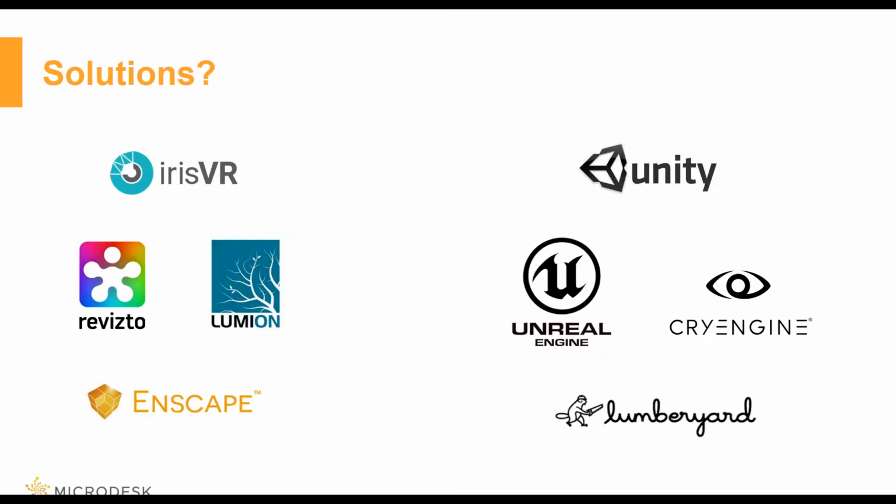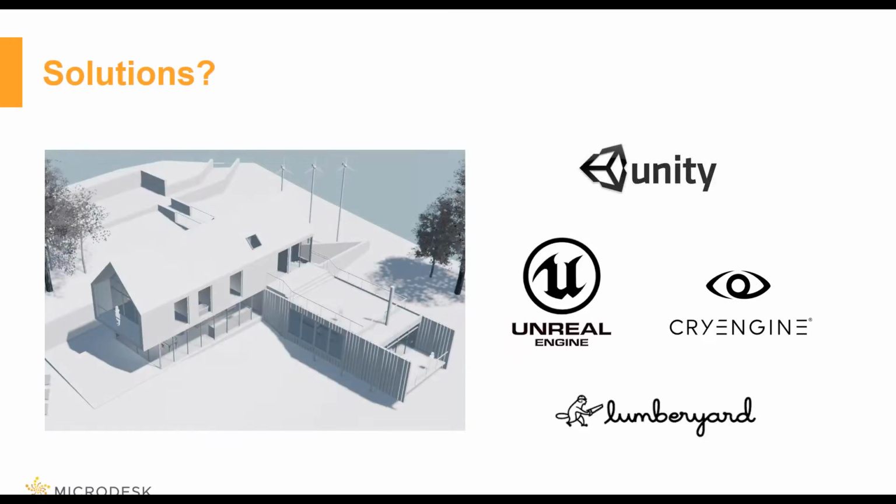And the problem that we tend to run into, though, is that if we want to actually add interactivity, and we're using one of the game engines that are listed here, you're going to have to deal with the materials. What I mean by that is that if I take a Revit model and I send it directly to one of the game engines here, I'm going to have to export it out, and that's fine. But what's going to happen is that it's not going to maintain my materials. It's going to need me to either reapply all of them, or it's going to need me to go through different steps inside of something like Maya or Max and essentially bake all of those materials into it. So if I didn't do that, I basically get what I have here. What looks like a big foam core model. Everything's all white or sort of a gray tone.